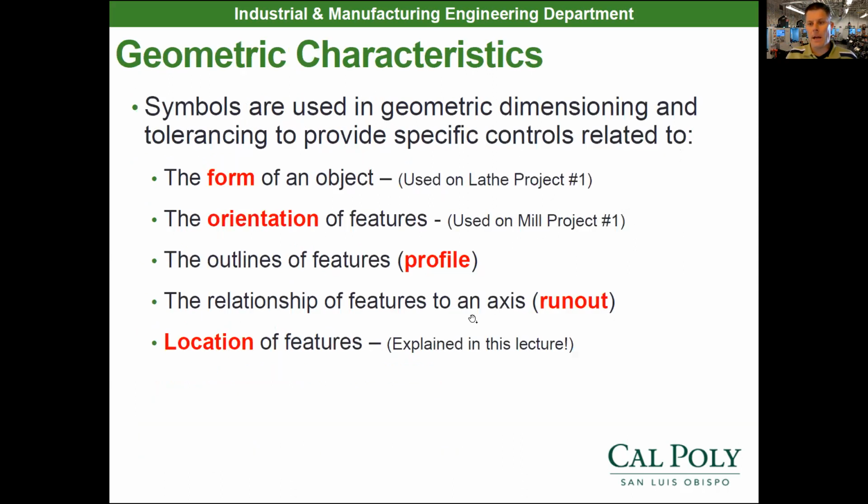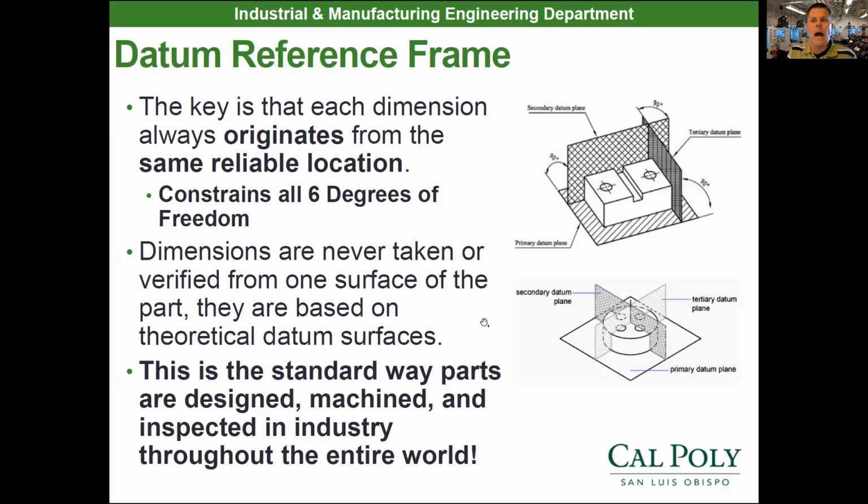So if you think about it like on my phone, the primary datum establishes 3 points. I set up a plane that my phone sits on in space, right? Well, the secondary datum's 2 points, a line, it takes away 2 more degrees of freedom, and then I really only have a tertiary datum stop, which locates all 6 degrees there.